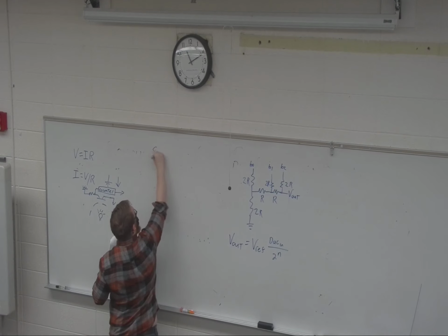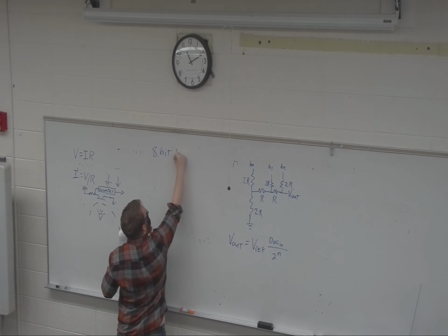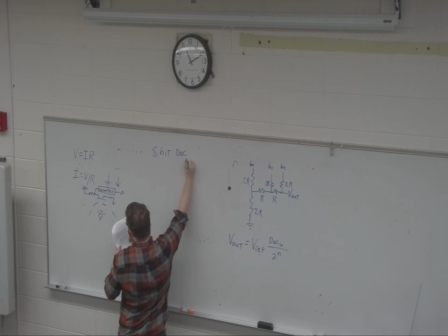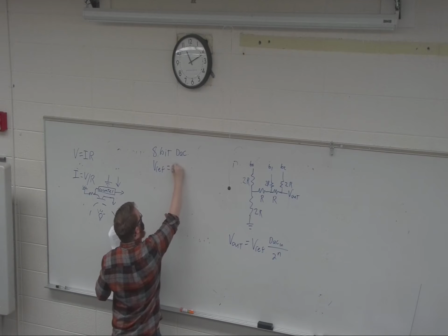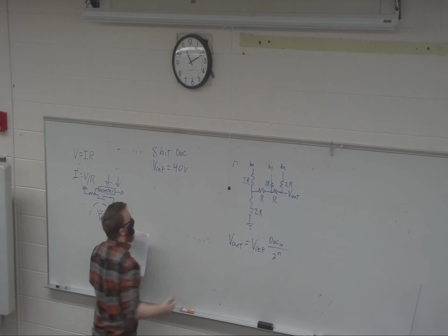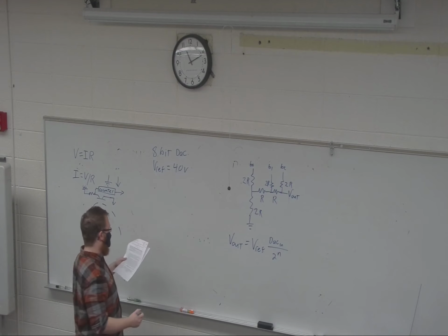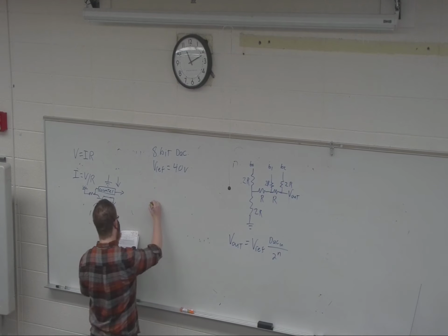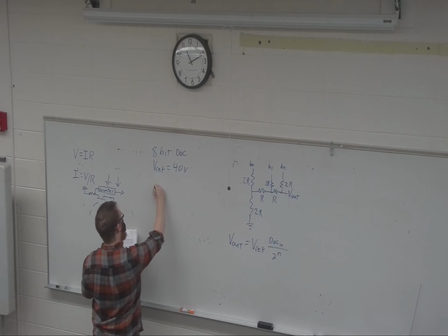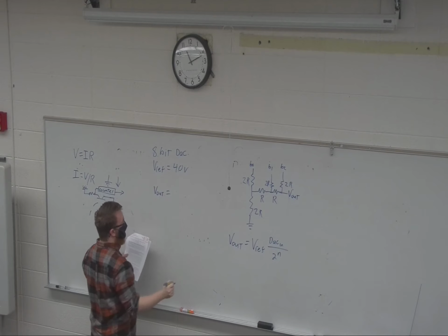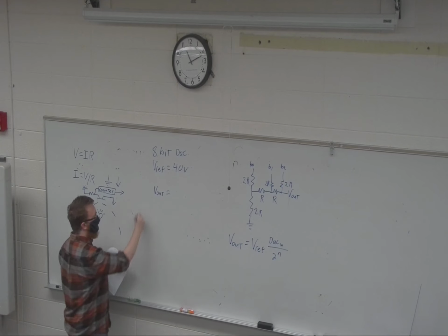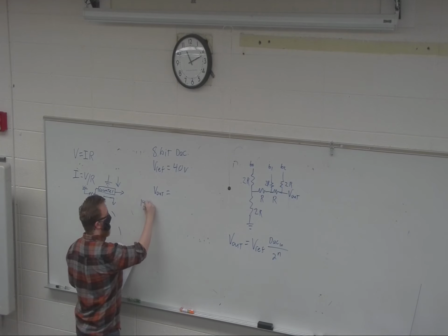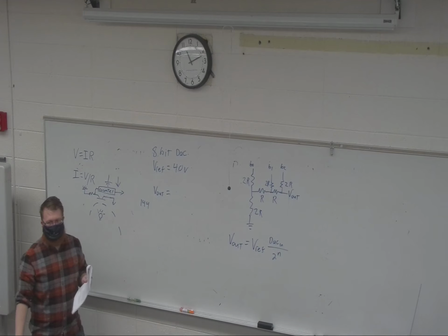So let's say we have an 8-bit DAC, and Vref is 4 volts. This is a silly example because nobody uses 4 volts, but let's go with it. How do I calculate Vout if the DAC number is 144?